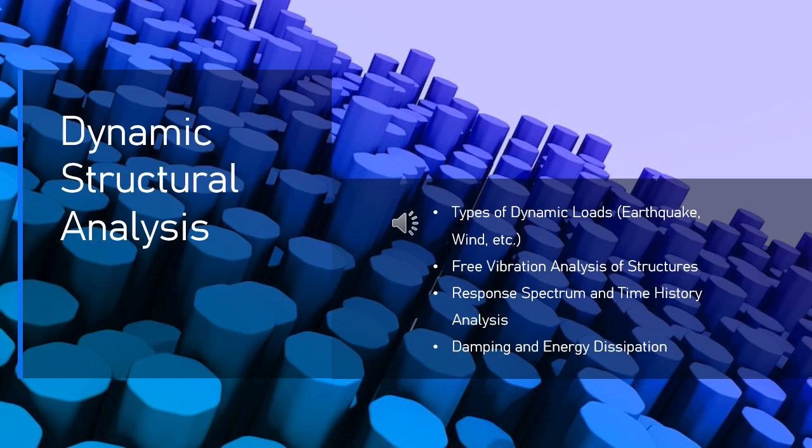How does response spectrum analysis work? Step 1. Modal analysis. First, the structure is analyzed using modal analysis to find its natural frequencies and mode shapes, as discussed in free vibration analysis. This step breaks down the complex structure into its vibrational modes. Step 2. Determine response spectrum. The response spectrum for the given dynamic load, such as an earthquake or wind load, is either obtained from experimental data, like ground motion records for seismic events, or computed from known excitation characteristics.